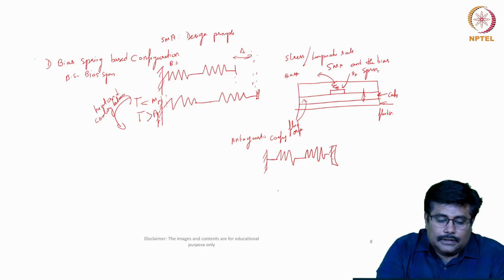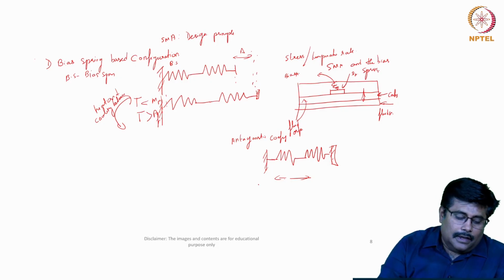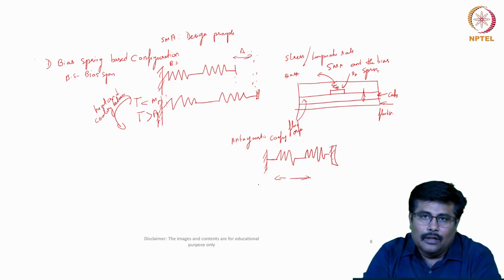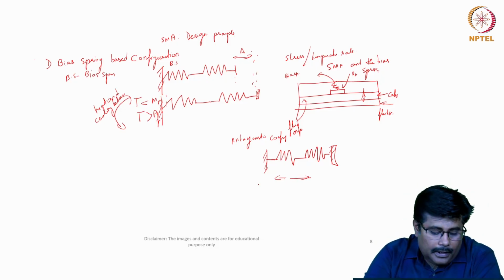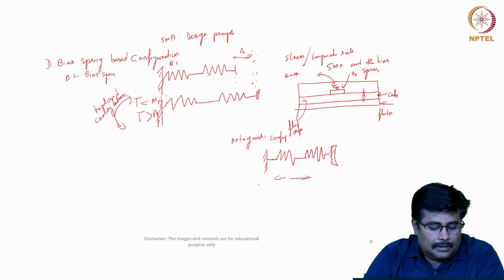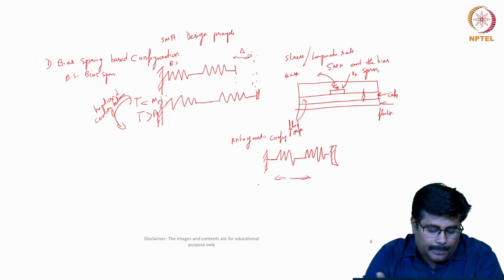There will be a set of configurations in such a way that whenever we need an expansion in this direction, the variant will be a simple bias spring actuator principle which uses two shape memory alloy elements. It consists of mounting two SMA actuators opposite to each other. As for the bias spring, the system consists of two coupled actuators that are first pre-stressed.